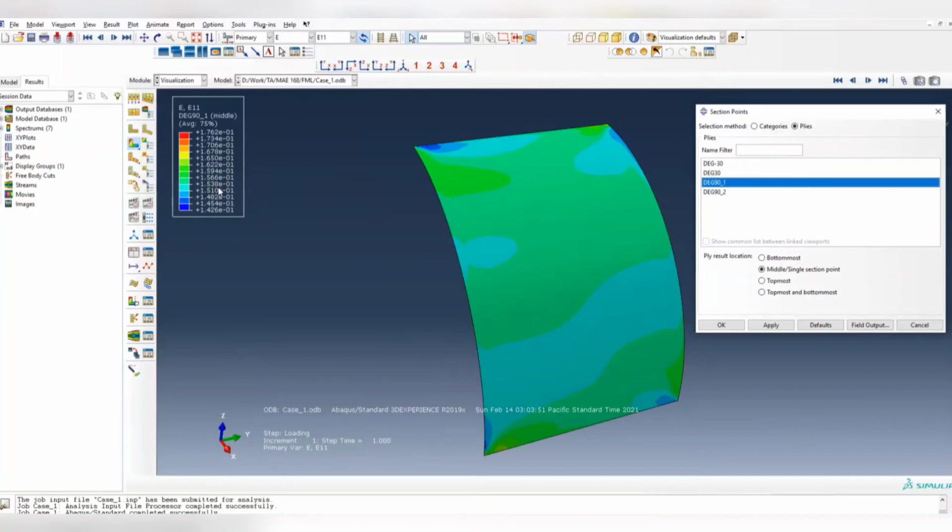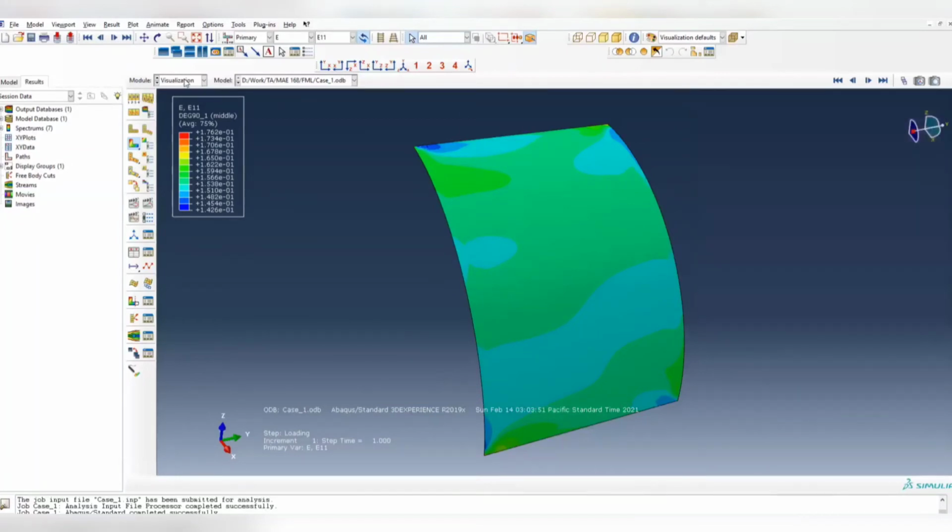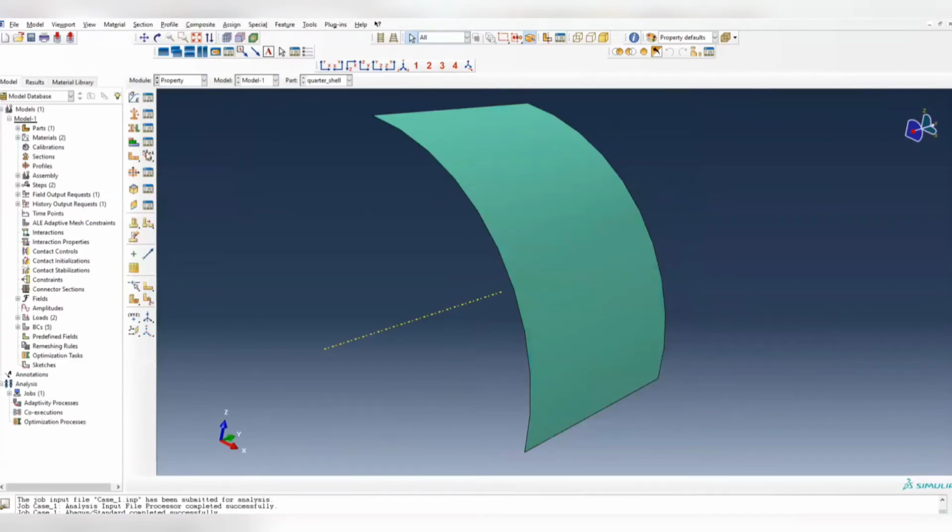So to reduce the strain to 1.5%, now it's 15%. So we need to have, this is almost 15.3. So it's almost 11 times the strain we want. So that means if you want to reduce the strain to 11 times smaller than that, you need to have at least 11 layers of your composite.